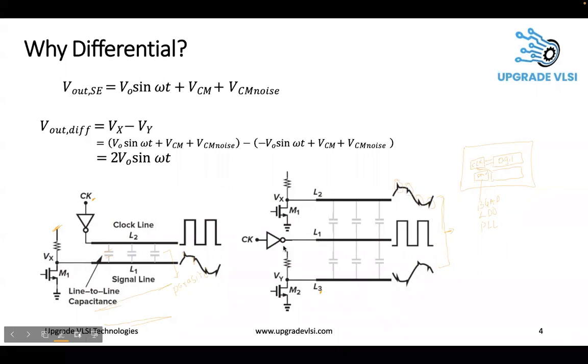So any digital signal or any noisy signal, if it is routing very close to the differential signal, then the common mode noise will definitely increase. But the differential noise will be like nothing. It will not have any contribution. It will be cancelled out.